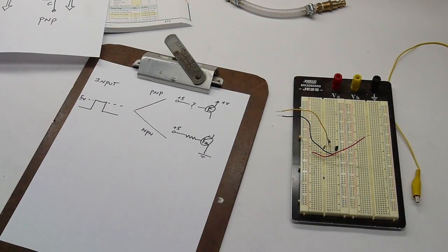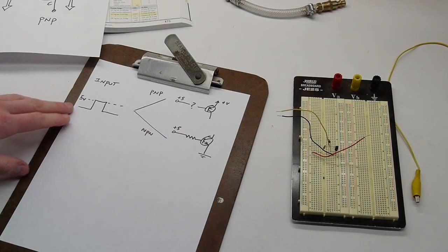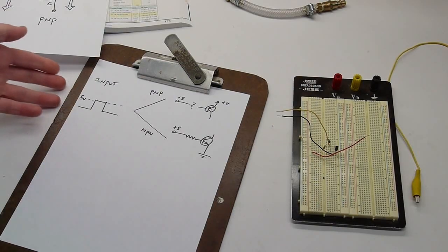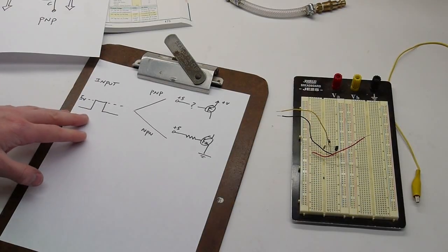Okay, so a minute ago I said that a transistor is a switch that is controlled by a current flow, and that we were trying to decide between PNP and NPN for our circuit. So how do we actually decide? In this case, the thing that's going to make the decision for us is our control signal. And in this case, it's going to be our favorite 0 to 5 volt logic signal. This could come from a microcontroller or a PC parallel port or a number of different things. So let's look at each case.